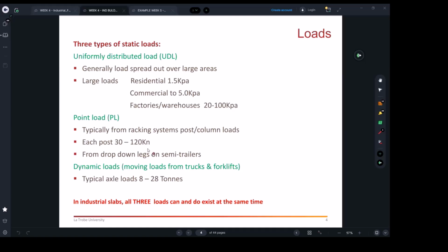They don't want to keep the dirt and soil over the construction time because it slows them down. If it's muddy, they can't move the vehicles and operate fast. So sometimes they pour the slab from day one, and then you have to know from the documents what the maximum point load is.